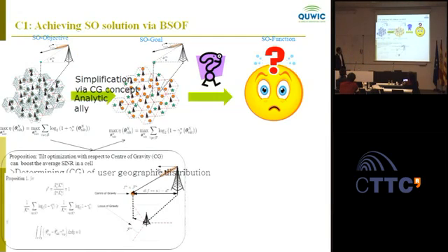Okay, thanks. So what we are able to do here is simplify our problem into a form which looks like this. From the tilt optimization's point of view, if you are a base station and you have to set your tilt, you don't have to look at all the users. You have to look at the centers of gravity, which you could calculate based on the SNR measurements if the user distribution is non-uniform, or based on the size of the cell and your own tower height if the user distribution is uniform. Once these points are known, your optimization problem has squeezed this summation. Here we had as many summation terms as users, but now you just have as many terms as the number of cells.